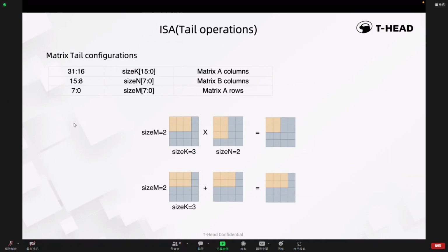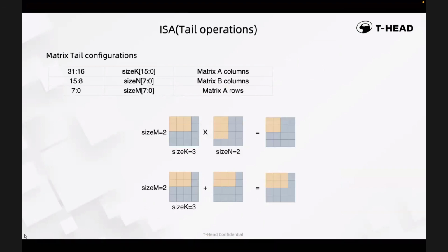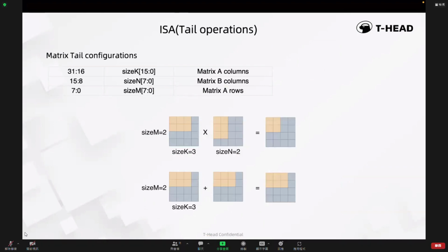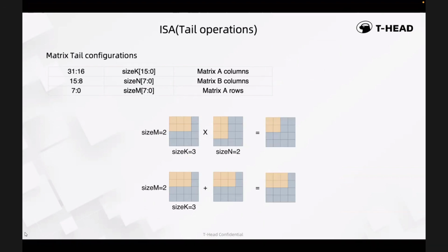The reason for asking is that if you do im to col, you have a large factor of memory expansion. So from whatever you need to convolve, you need to expand into memory. There's going to be like a 4 or 5x expansion in terms of size. And then you have to read it back from memory and then process it. And usually there are some neural network engines that do that on the fly and they avoid reading and writing the memory and causing that expansion.